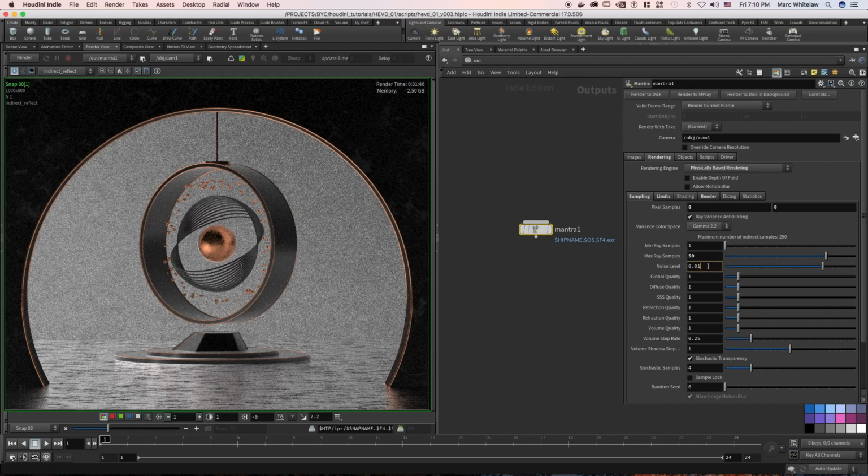If you are still getting noise, it means that it might reach this noise level at, say, 30. Once it detects that there's only this amount of noise left, it's going to stop casting its rays. That's why you might be oversampling different areas if you keep pumping this up and you're still getting noise, because it's cutting off. This is essentially a threshold.